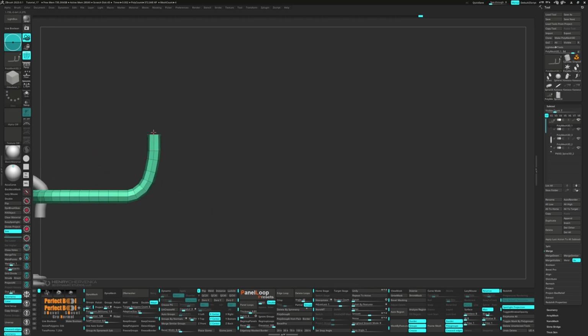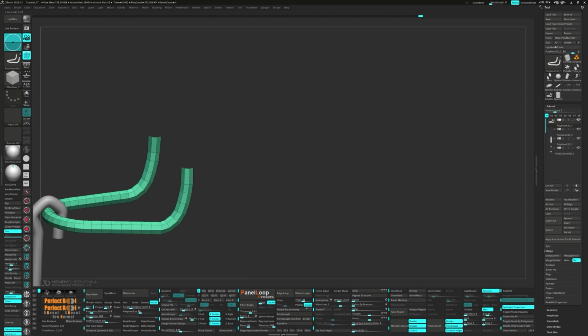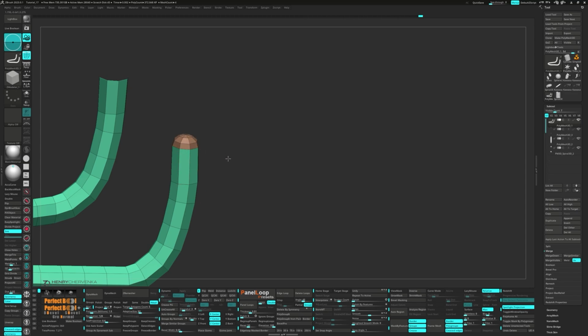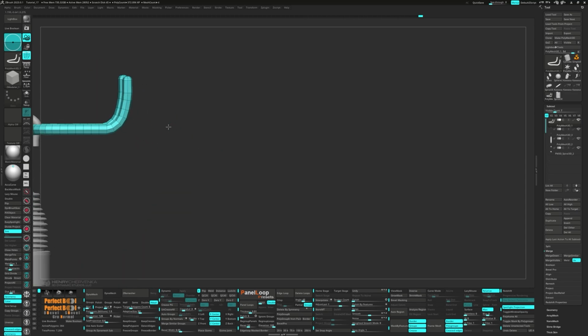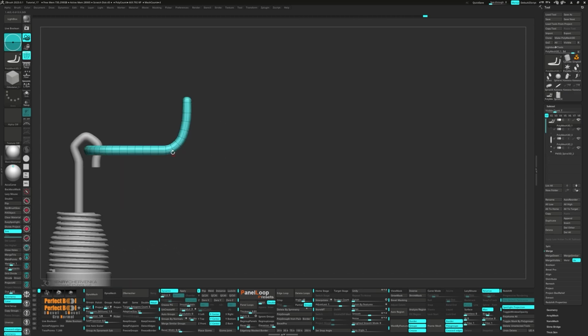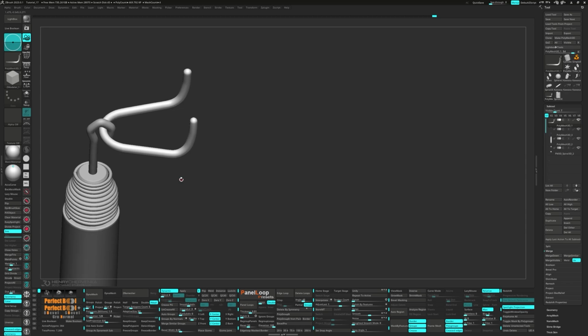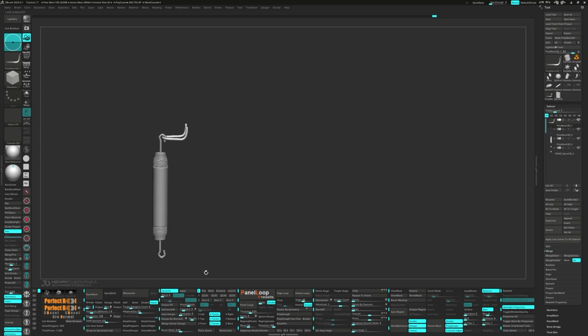Again from the ZBrush, pick Close for the edge action, Convex Hole and Circle for the target, and Interactive Curvature for the modifier. We can just click to repeat the operation. Press Ctrl W to group visible, then turn on Dynamic. Unmask the polys and run a polish by features. Now we can weld it along the x-axis.